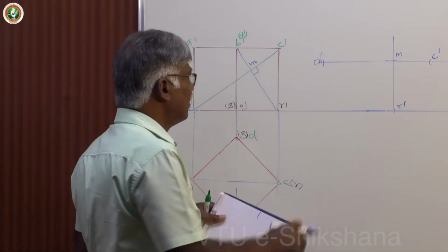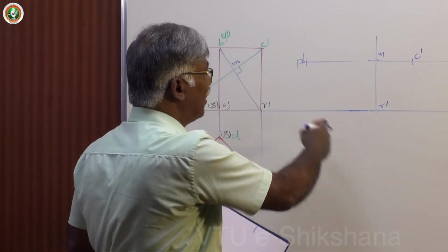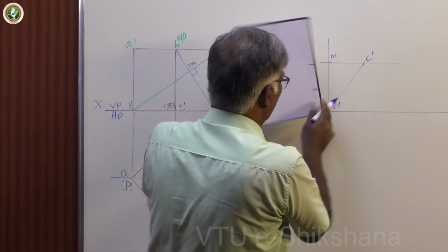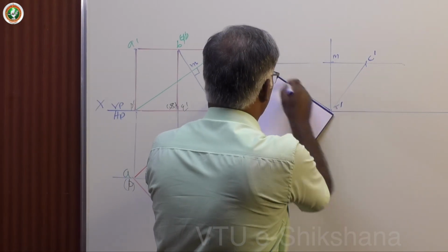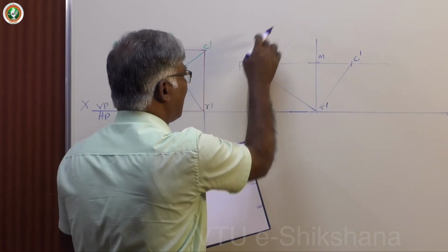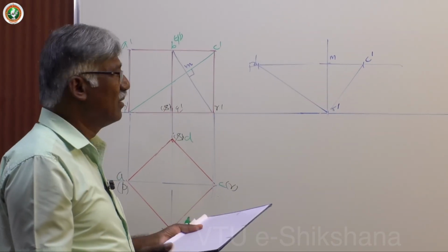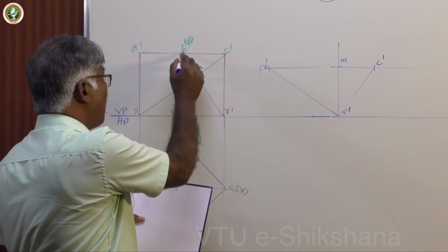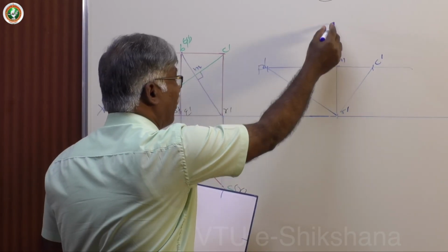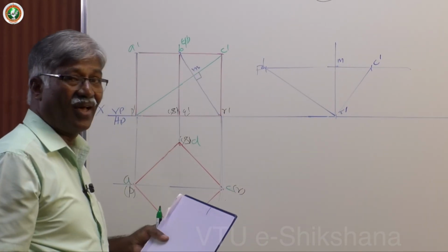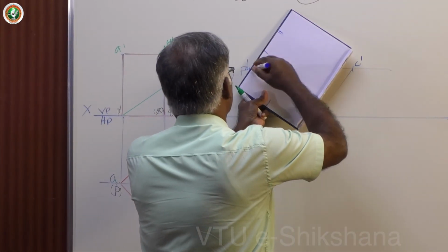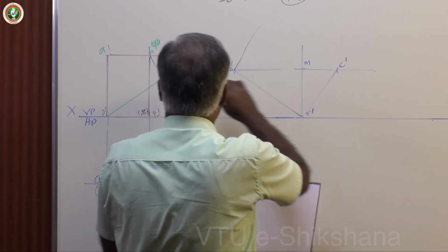Okay, next, how to complete? You finish the rectangle out of this. See, you join R and this is another line. You make parallels to this line and this line, that's all. Geometry. At the same time you see that this projected point, the vertical line should catch this, otherwise it is wrong. Now draw perpendicular again, or you do the arc method.